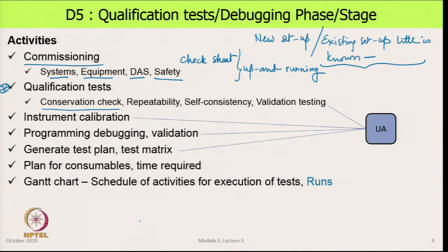For example, if we are measuring flow through a pipe and you have measured the velocity at this point, and on the outlet we measure the velocity at some point, we may be interested in the velocity, but before we can confidently say what is happening to the velocity, we should be able to convince ourselves from first principles that the mass flow rate of the fluid going in is equal to the mass flow rate of fluid coming out.